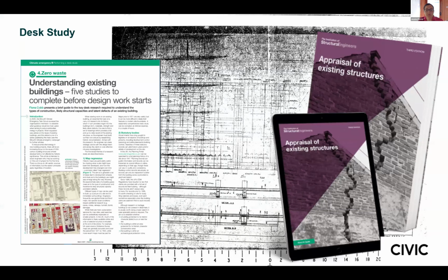You're trying to get an overview of the building as a whole, and generally the first step in developing this understanding is the desk study. Ideally, this will tell you what you might expect to find in the building, the likely construction type, age and history, and therefore its likely loadings, as well as the potential for maybe bomb damage or alterations and change of use.